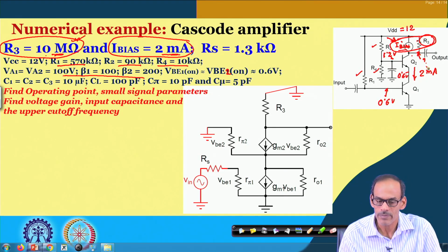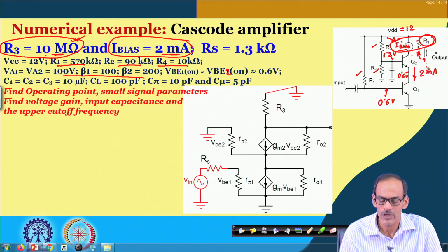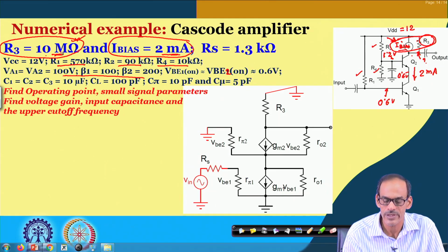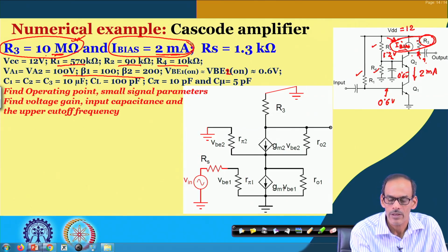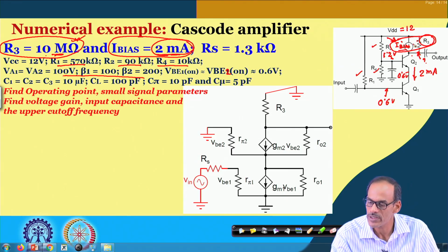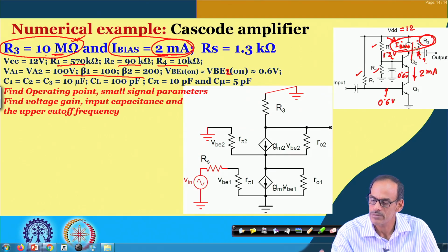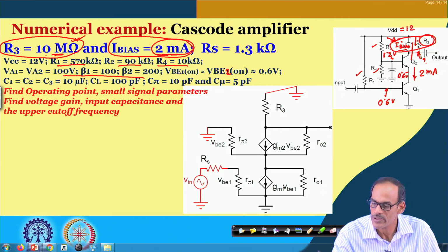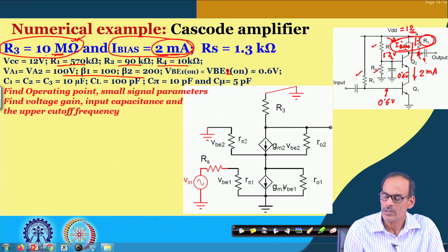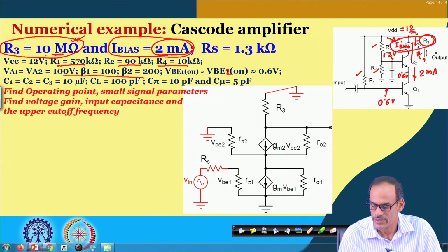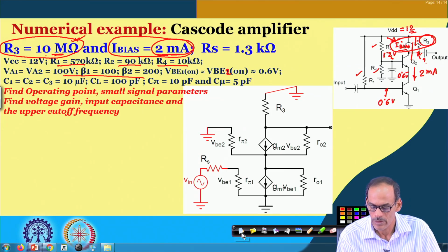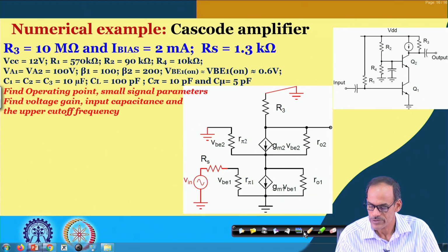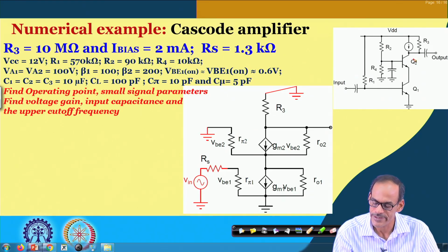In fact, if you see the value of the resistances here, and if the current here is 2 milliampere, getting supported by this bias current, then the current flow through this R 3 is 0, so the drop across it will be 0. Naturally the output voltage will be 12 volt. On the other hand, if I consider the practical circuit, let me use a slight analysis here.